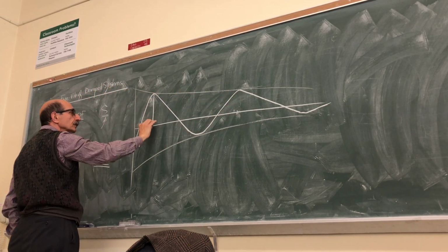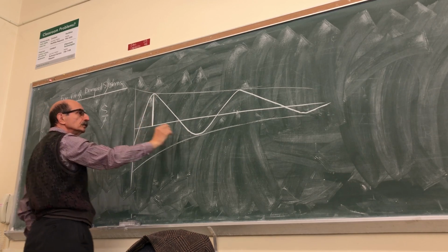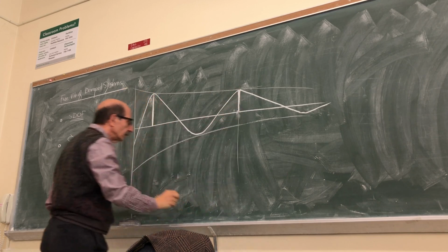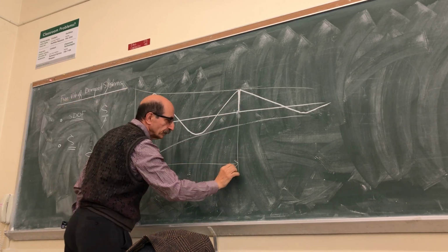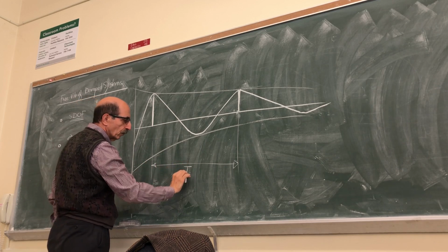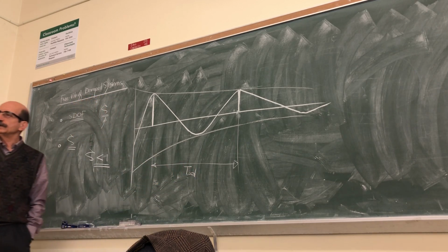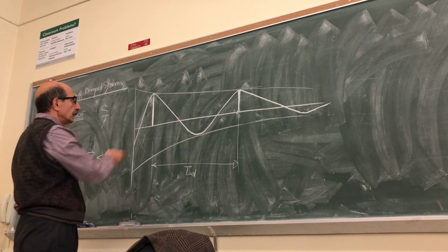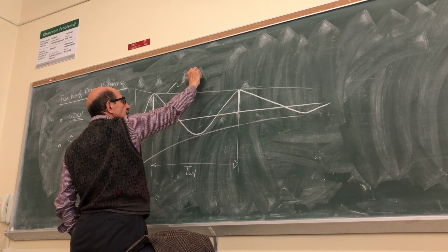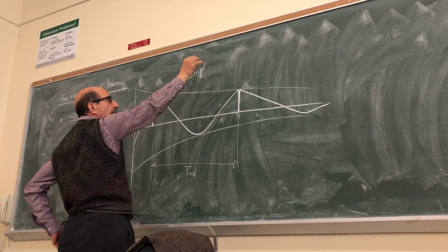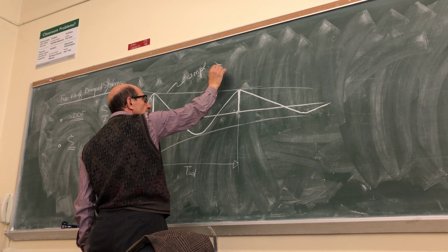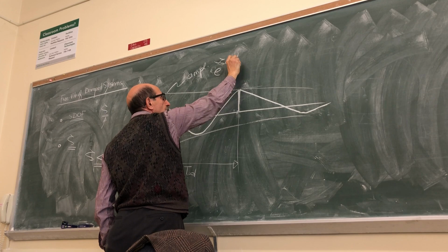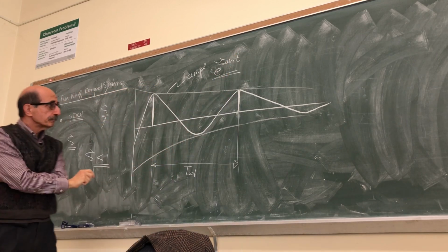So now let's recall, we look at two consecutive amplitudes of the same sign. The distance between the two, as we know, defines the period of that oscillation, right? And this is, of course, the amplitude. You remember the amplitude was an exponentially decaying function, okay, described by this.